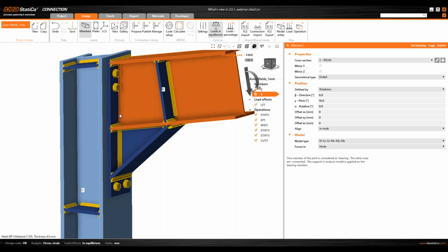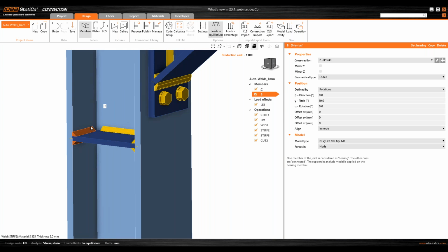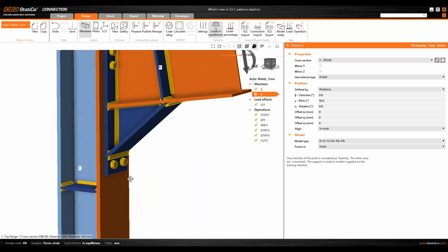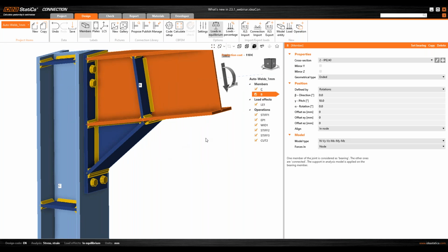In the bottom part of the screen, you can see 4 millimeters, or right click, and you can see it here as well, 4 millimeters here. Right click on this weld, it's 6 millimeters here. This one, 7 millimeters. So I'm not saying that everything has to be designed for full capacity of the plate. That's not the point. The point is it would be recalculated for you automatically.